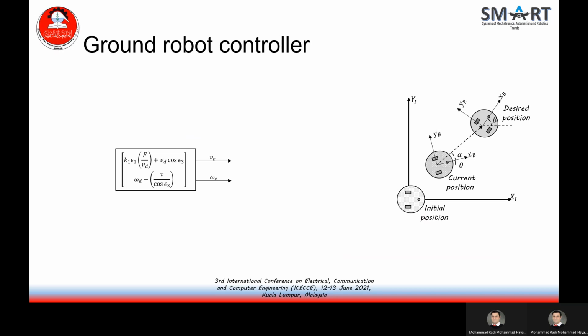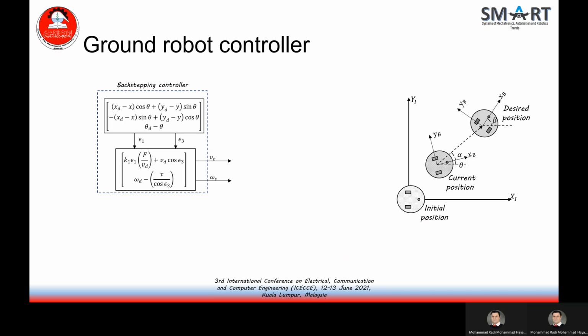The aerodynamics is required to complete the control law, which is defined by the difference between the reference trajectory and the current position. Then, by mapping the robot kinematics and the motor motions, we get the required speed of each motor. After that, the motor model with a PID controller is considered for motor voltage regulation.